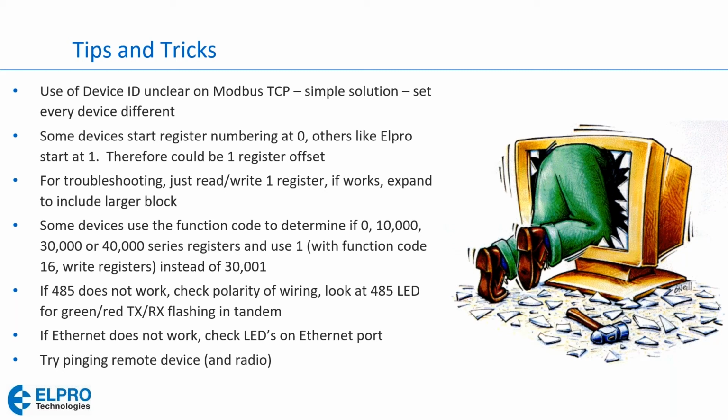So there is something there, but it's outside of the scale of 0 to 20 milliamps. So the Modbus mappings will be successful, and it'll be up to the external controller or whatnot to realize, oh, that's an out of range value. I know this mapping is successful, but there's an out of range value in it. It probably just has not been updated as of yet. Okay.